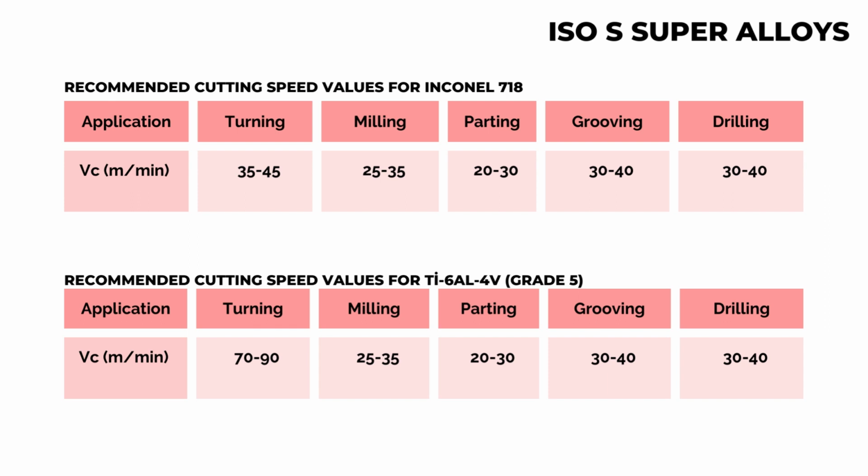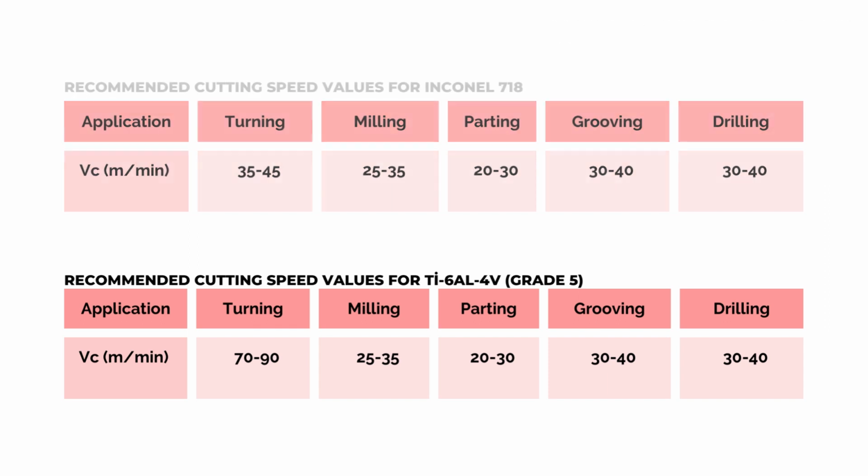It should be machined with positive and sharp cutting edges. Geometries that are suitable for austenitic stainless steel will also work well on heat-resistant alloys. However, quality manufacturers will have different geometries specifically designed for nickel-based alloys in their catalogs.